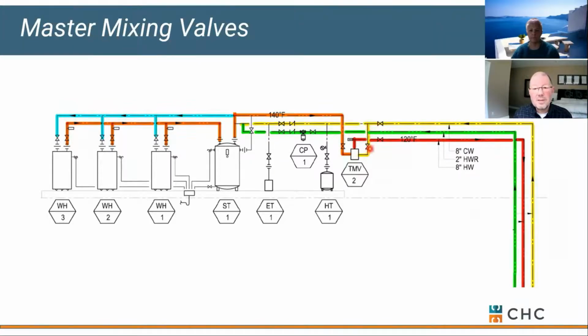That city water can either get into the cold side of our tempering valve or master mixing valve, or it can continue over where it ties into our storage tank, picks up some hot water, and brings that hot water into the hot side of our tempering valve. Hot and cold mix to give us tempered water to send down our riser so we don't burn anybody in the process, but there's hot water available. All that's great.